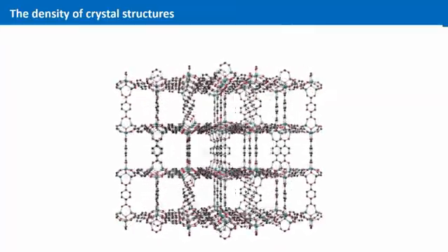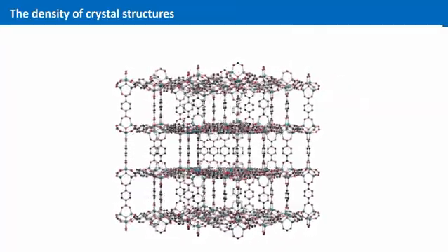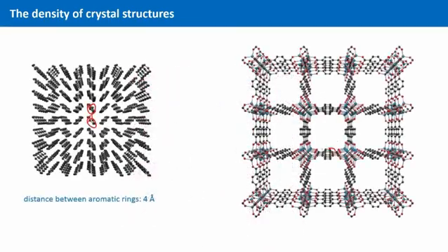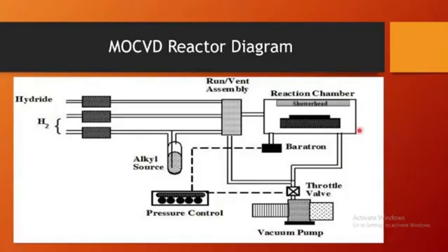Also, the metal organics are compounds where each atom element is bound to one or more carbon atoms. MOCVD uses surface chemical reaction, which is the transport of precursor molecules by a carrier gas of hydrogen or nitrogen onto the heated substrate. The process starts with injection of reagents into the reactor chamber through separated orifices in a water cooled shower head injecting molecules. A homogeneous gas phase is achieved at 5 mm below the shower head.